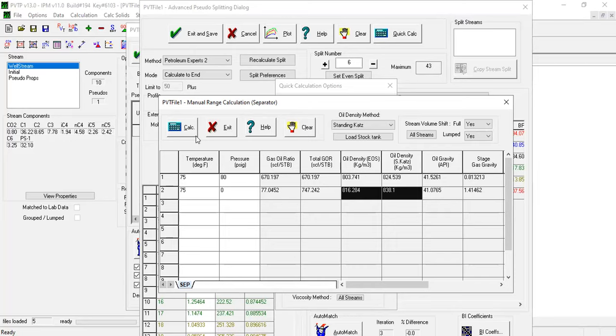It is also possible to deviate from the reported composition profile to obtain a better match. However, deviating too much may result in certain objectives, such as tracking the evolution of the C7 plus components over time, not being met, as the model composition is not representative of real life.